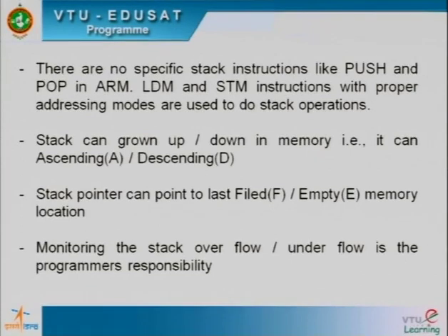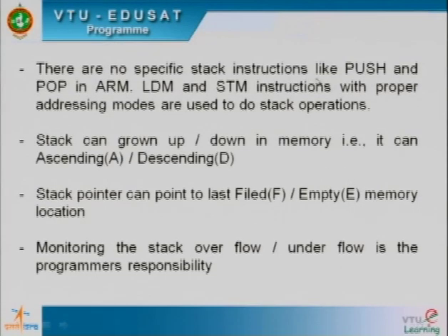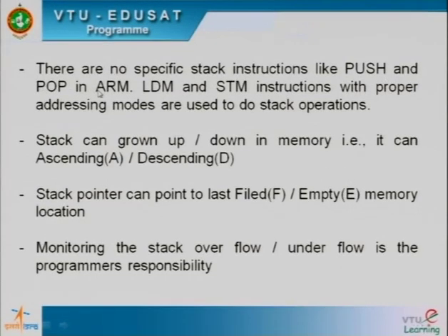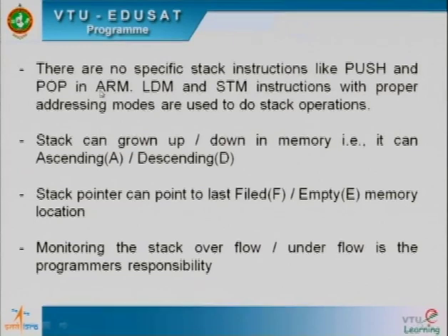What does ARM provide for stack instructions? There are no specific stack instructions like push and pop in ARM. The ARM instruction set does not provide specific instructions like push and pop, like any other processor does. What it provides instead are LDM and STM instructions with the proper addressing modes. We'll see what we mean by proper addressing modes in the next slide.